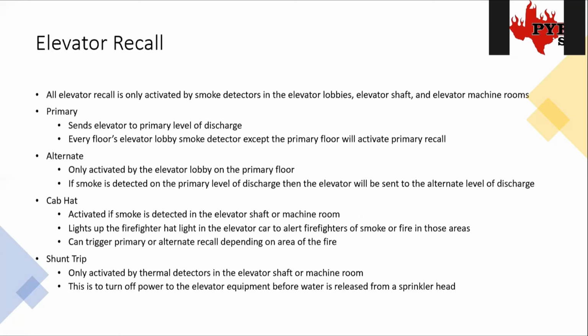In City of Houston specifically, if you do have shunt trip, they require a delay on it that allows the elevator car to go all the way to wherever it's recalling to, whether it's primary or alternate. It'll go to that floor and then open the doors. And once the doors open, then they want the shunt to happen, because they don't want it to lose power like halfway between floors with people in the car.